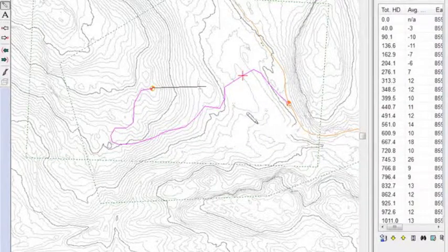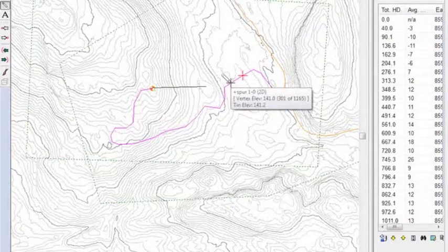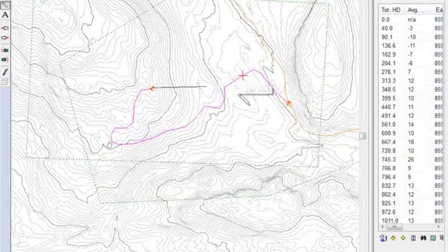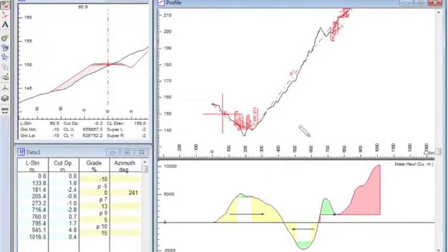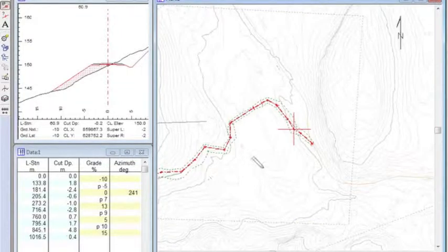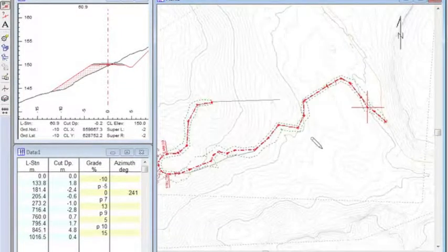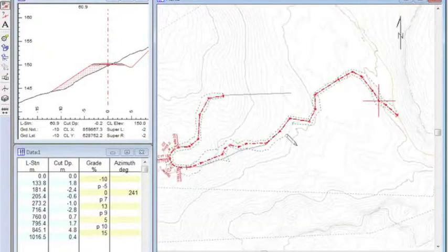However, the LiDAR file doesn't contain any information about the soil, the ground wetness, seeps, stability. It's just not in there. So although I can design a road and get to the point where the location design is creating a pretty reasonable final design here, I mean, I could go out and build this. I still don't know whether it's feasible until I walk the line.